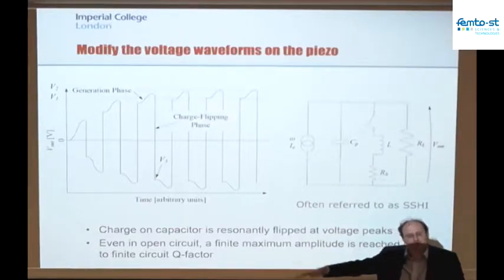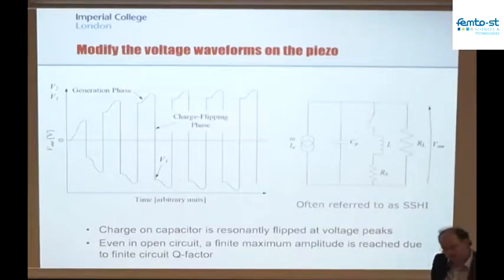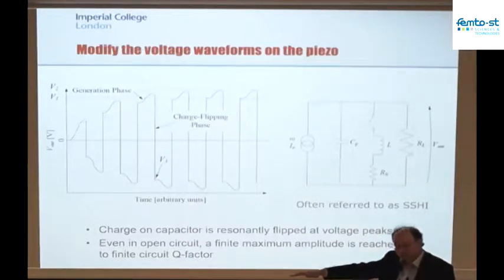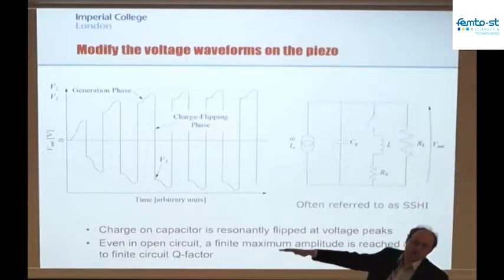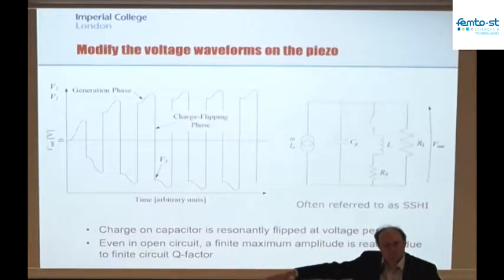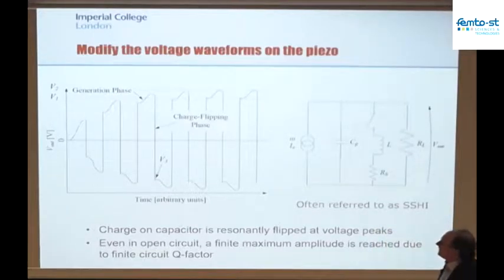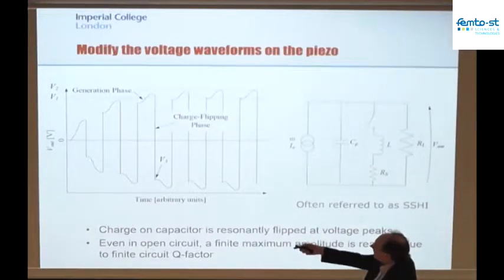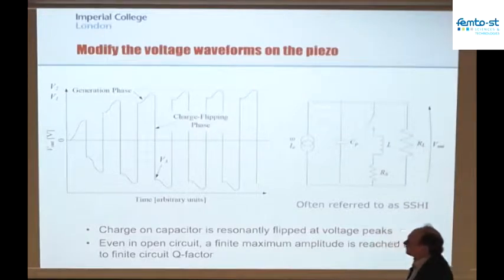It's a spring which is being deflected. There's a spring constant inherent in that material and the beam and the substrate, which is trying to pull it back to the center. But the creation of the charge displacement and the voltage, therefore, on that piezo is also pulling it back in the same direction. So if instead of allowing that voltage to just oscillate sinusoidally, I chop the voltage and have it behave like this, going from one point to another, switching the voltage, what am I effectively doing?